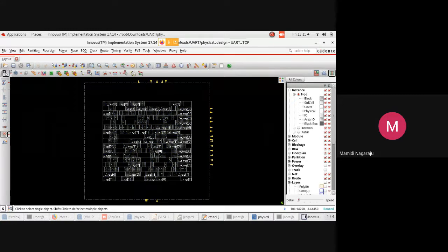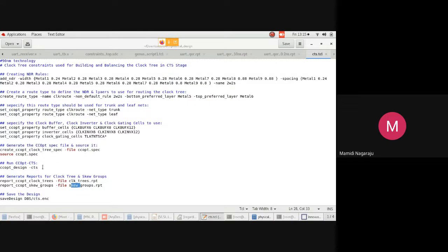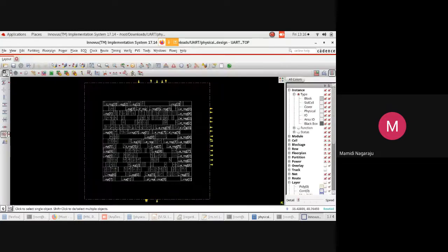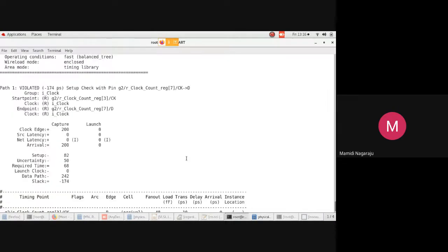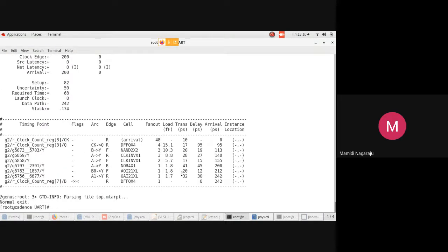Now at this stage, I'm just showing this clock, and then saving the design as CTS encounter. With this name, it is saved with the stage called CTS stage. Okay. Now remember, tomorrow when you want to open your design after CTS is complete, you give this file, and it will be invoked where you stopped your design. Okay. Once the design is ready, I'm just keeping all metal layers on. Now I'm minimizing, and giving the design command from here.